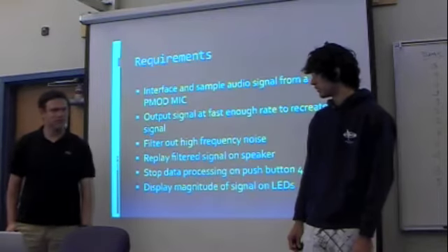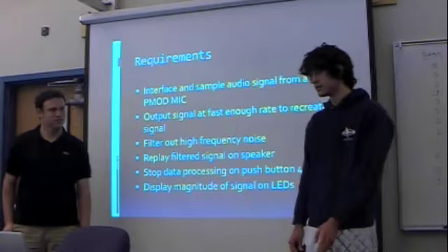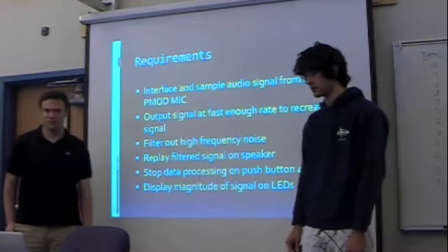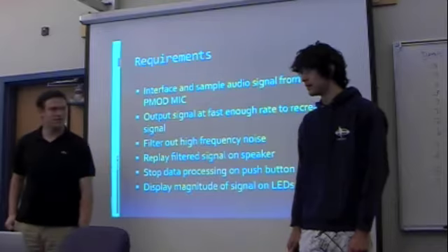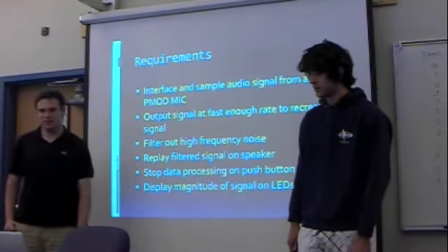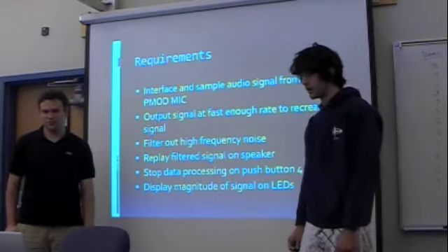We took it in at 20 kilohertz, so the highest pitch frequency is 10K, which is higher than normal speech. I'm probably speaking at 100. We filtered out high-frequency noise, which we seem to have a lot of when we first tried to output the data. And then we send the filtered data to a speaker.